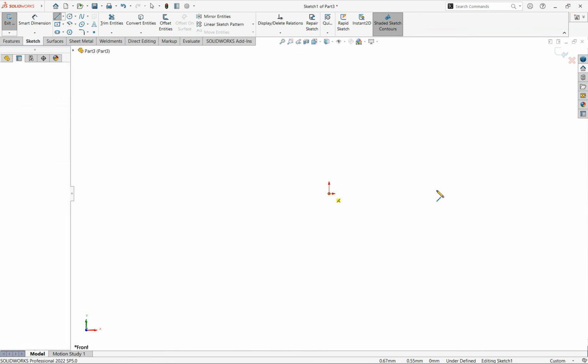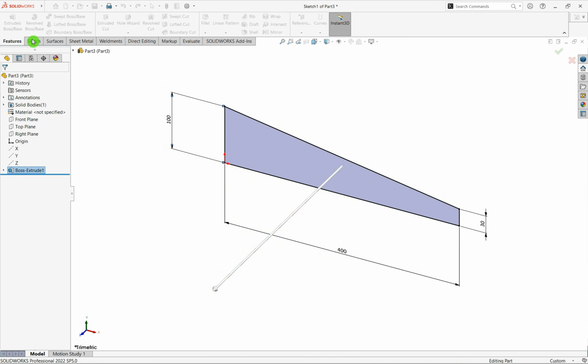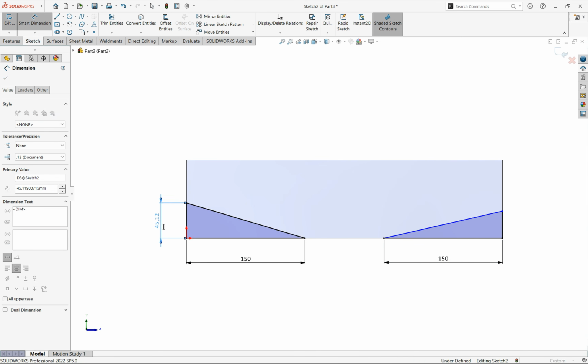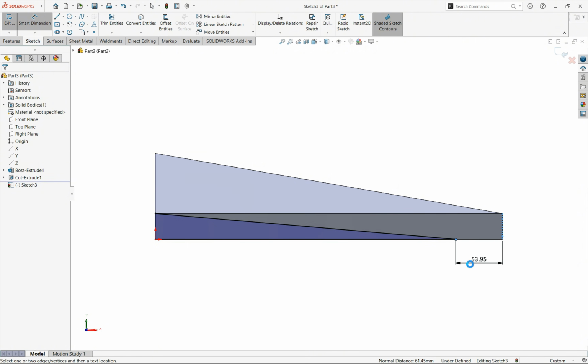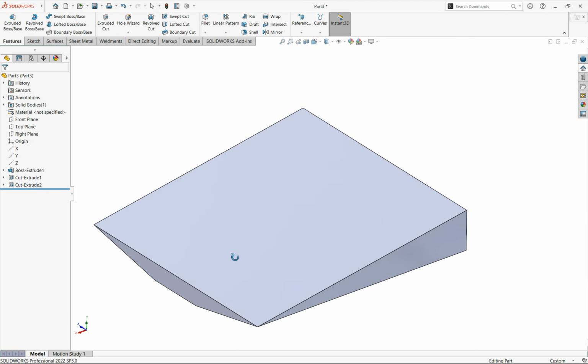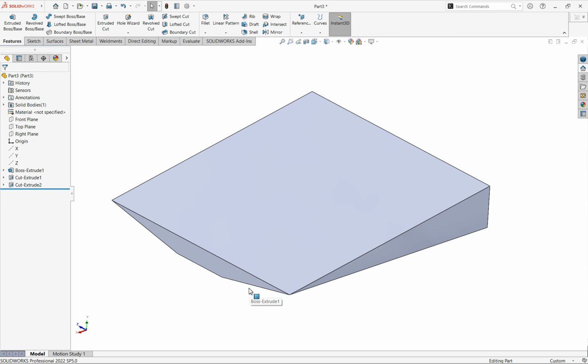We will start by creating the boundary of the sheet metal part by creating a solid model. As in most cases, we start with a sketch. This gives us the most control in dimensioning. The Boss Extrude feature makes it a solid model, and by applying a few more features, we have our solid boundary representing the geometry of the sheet metal product we would like to have. Now the real work starts.